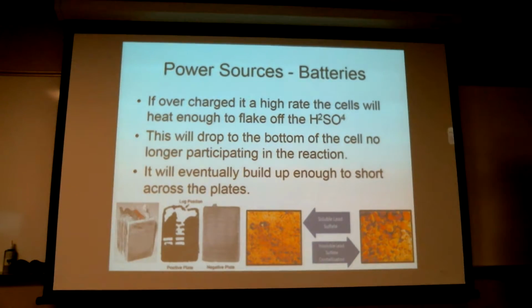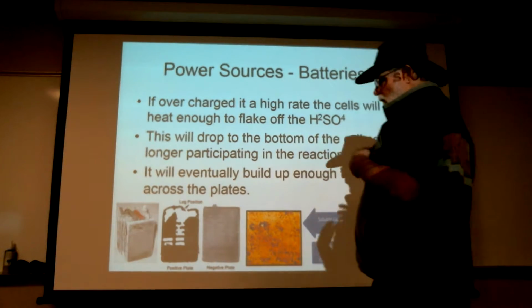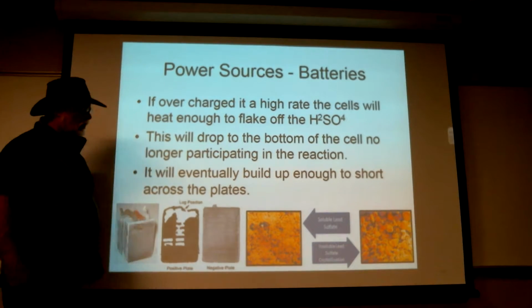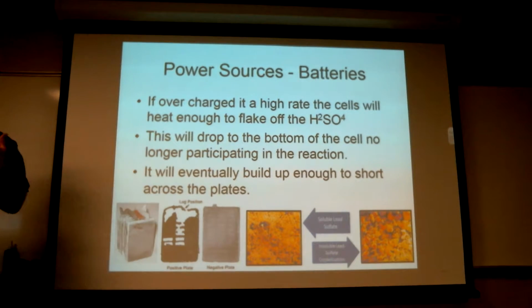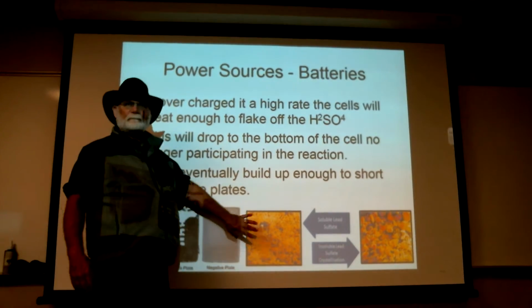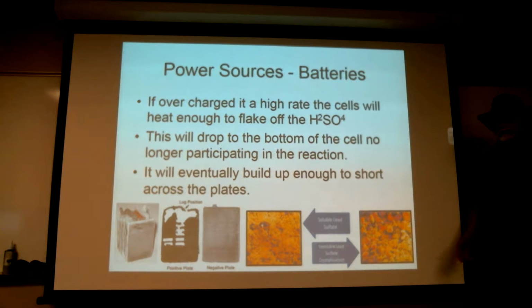What will happen also is, as the battery starts discharging, its lead is turning into lead sulfate. Okay, both plates, lead sulfate. You want that lead sulfate to form into small microgranules that will easily dissolve back into lead and sulfuric acid in an electrolyte. This isn't a very conductive substance. It needs to be somewhat conductive for the electricity to cause it to recharge.